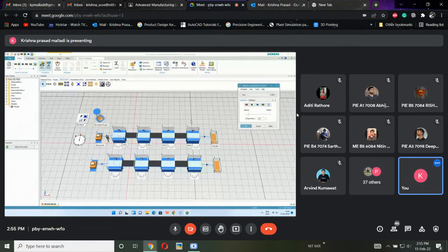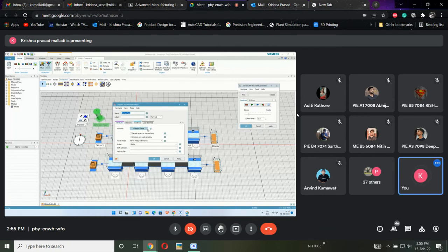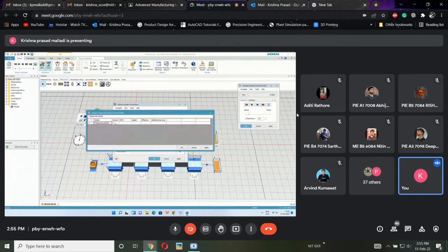Now, have a look here. What is happening here? Because we have assigned only one worker. By default, if you reset the simulation and click that worker pool, there is a creation table, and the default is one worker. So if the workstations are 100 and you haven't changed this, one worker will have to work on 100 locations. That is what is going to happen.